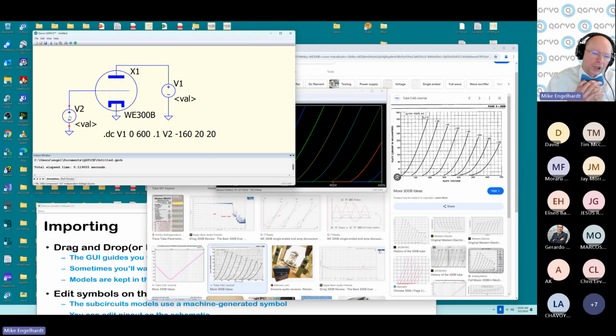For wire connections, the wire connection grid is 100. So you could have something at 0, 100, 200, 300, and the graphical objects can be within 100th of that. That lets you draw with a great deal of precision. If you make a symbol, if you can draw within 100th of a wire grid, basically there isn't anything you can't draw.